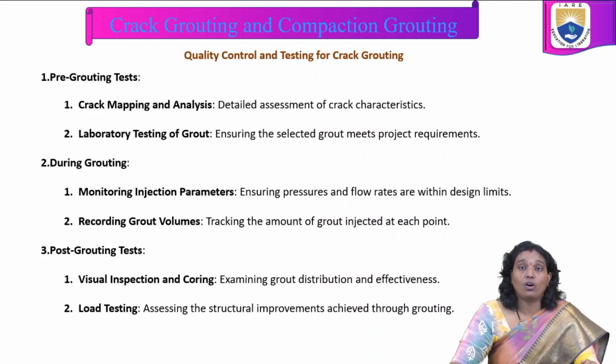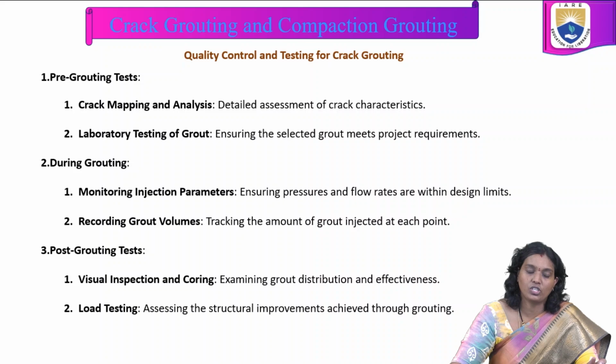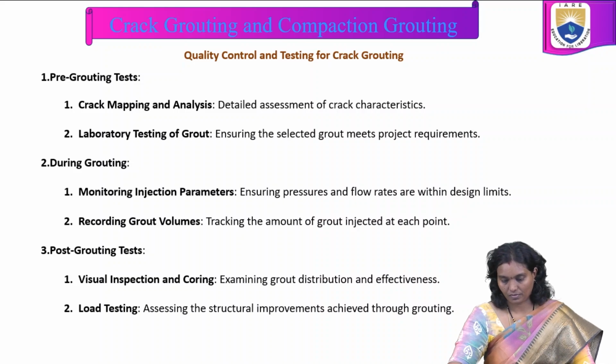Coming to recording grout volumes, tracking the amount of grout injected at each point. Post-grouting tests are visual inspection and coring, examining grout distribution and effectiveness, assessing the structural improvements achieved through grouting.